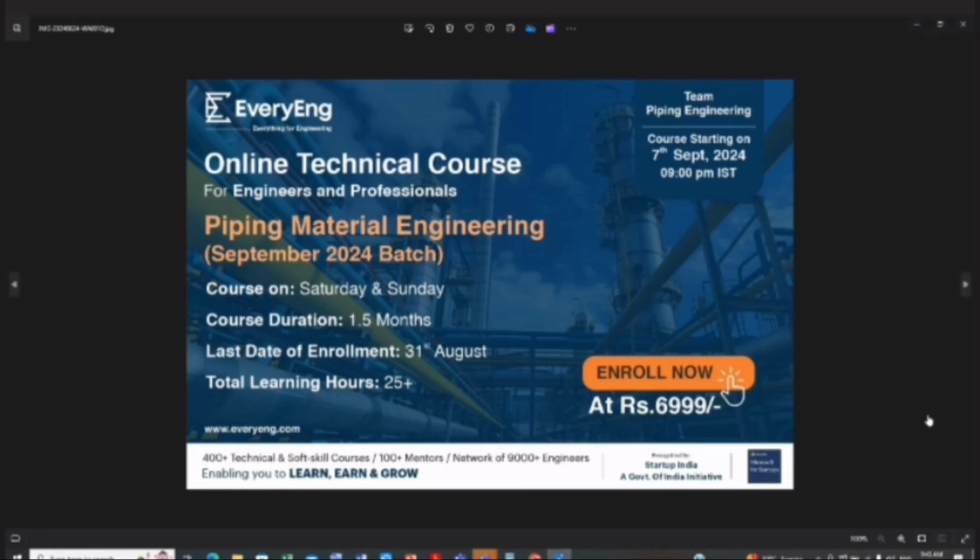So we have this session which covers the main topics of the piping material engineer, in which we will not only explain, we will teach how to prepare the PMS, how to prepare the VMS, what are the different piping components, and the small details of the components, like how to select the rating, how to read the PT rating chart, how to do the wall thickness calculation, internal pressure calculation, the branch calculation, paddle blank calculation, and also requirements like PWHT, radiography, impact testing.